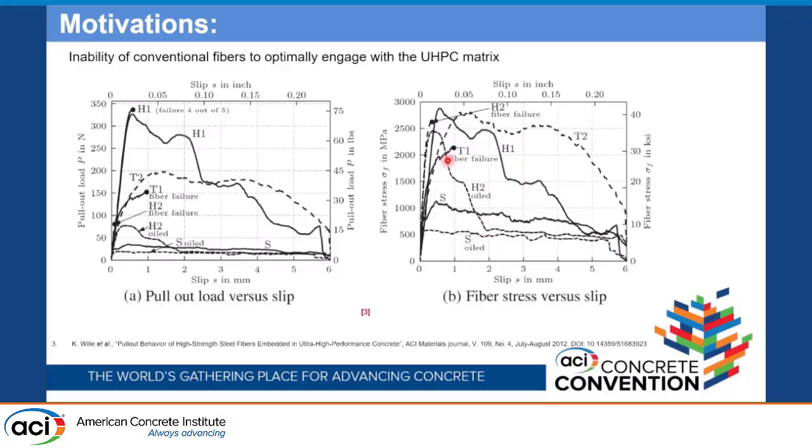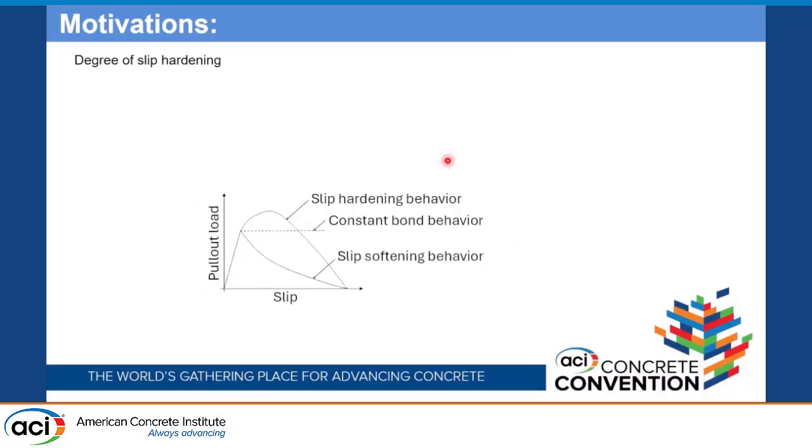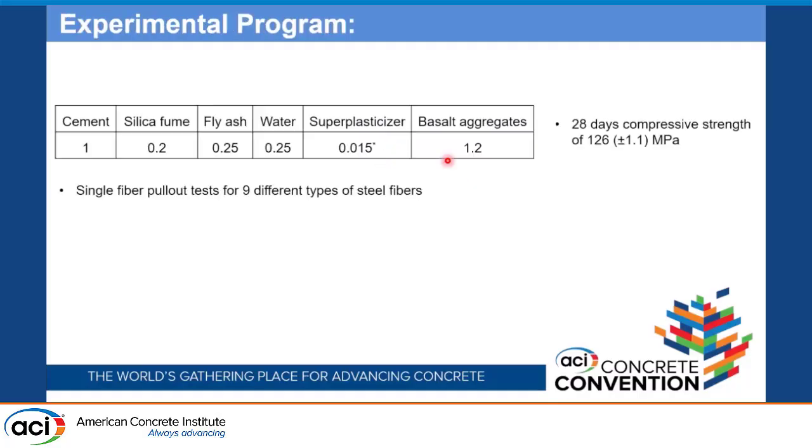Now the second motivation is to find the degree of slip hardening. We desire to have a slip hardening behavior, which can be confirmed visually, but there is no equation to quantify it yet. So we will propose an equation to quantify the degree of slip hardening.